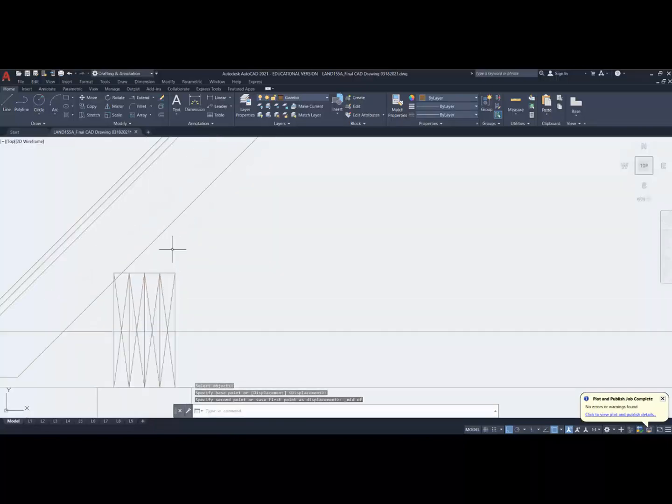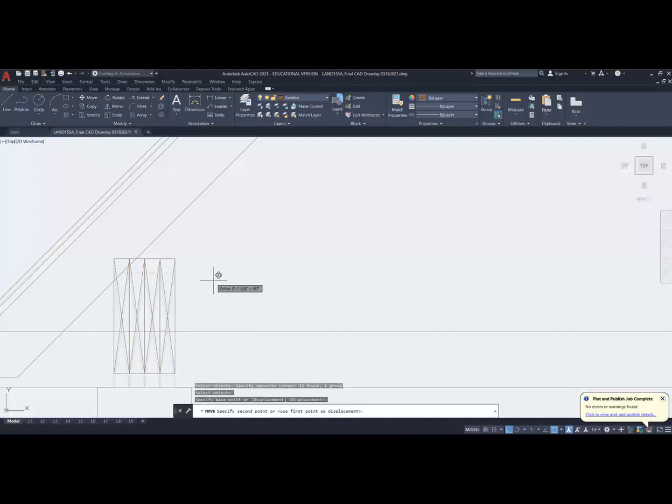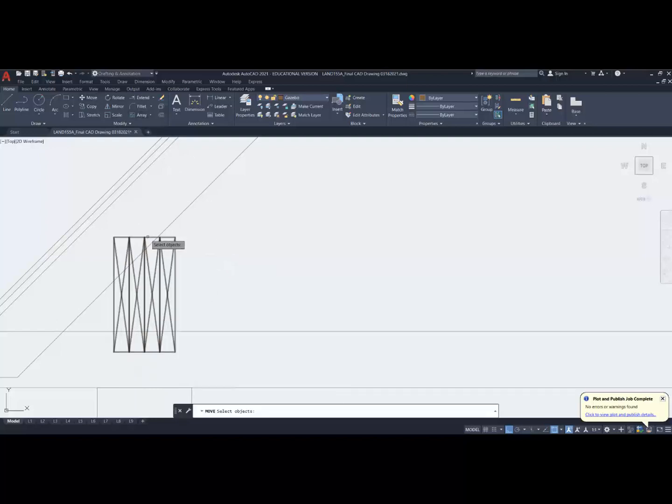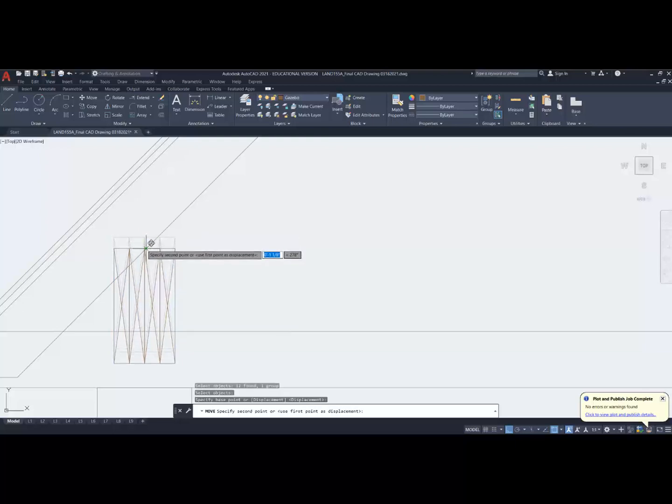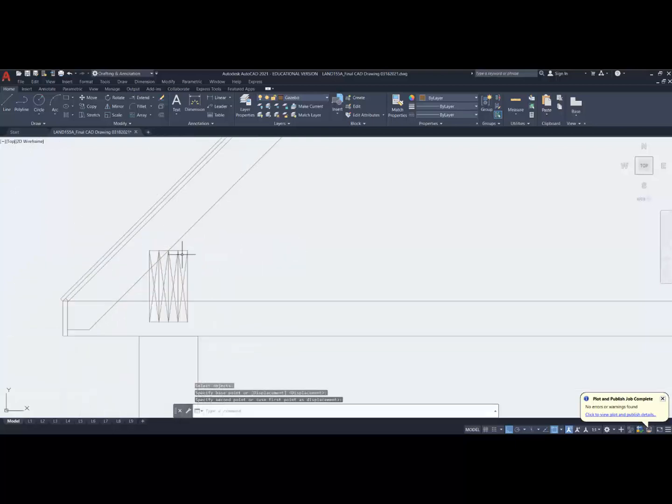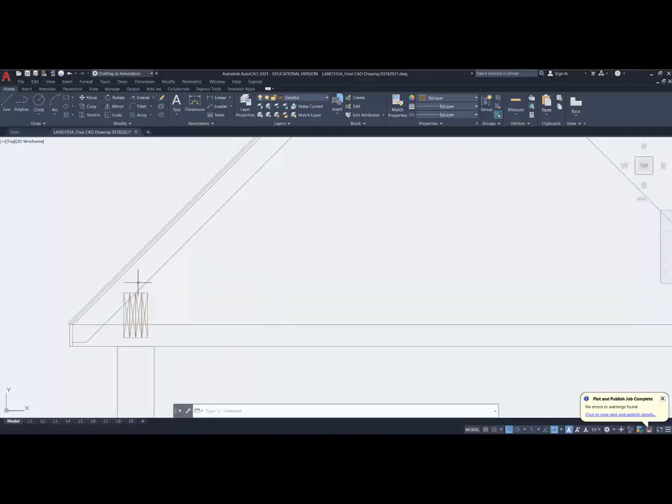Now, how high does it go? Well, the way it goes is basically we want to move this so I have at least 3 inches of the joist sitting on that product. So I'm going to move this upwards, and that's the minimum. See, those two are 1.5 inches thick each. That's the minimum. If I bring it way up, I've cut too much into the joist. So that's the height I want to put it at. So I'm going to go beyond the edge so then I can move it from that midpoint down to where it intersects. Now, if I needed a wider ceiling joist, let's say an 8-inch, which is 7.5 inches.